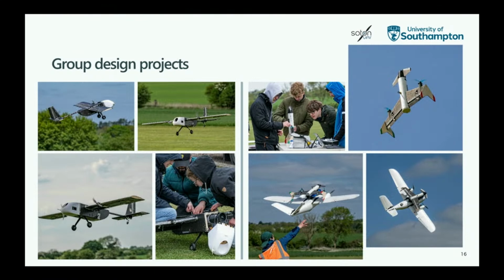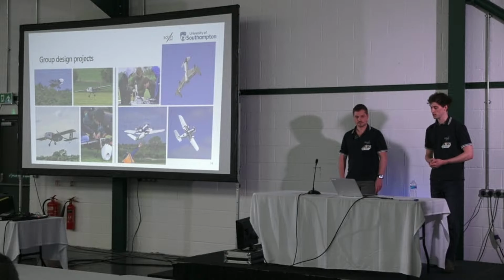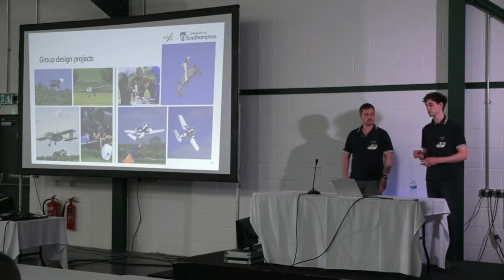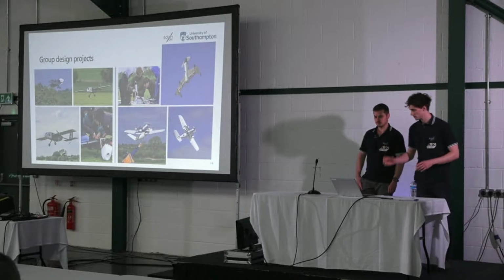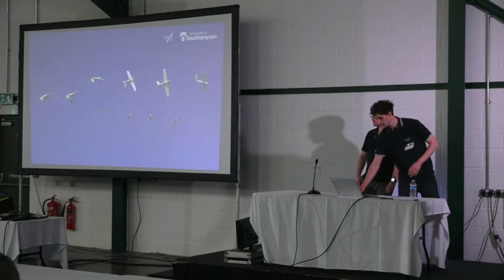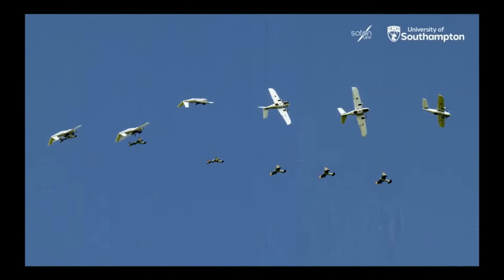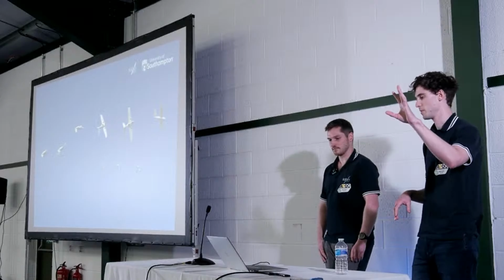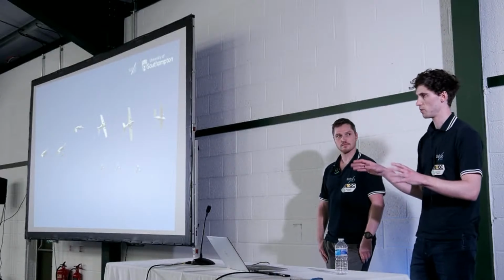The transition flew around, could do waypoint missions, come back, and transition back to its tail sitter configuration for a nice precision landing. This team went above and beyond and designed a release mechanism, attached it to this Believer aircraft, and then in quite a shuttle-esque fashion, we have the release there. The Believer would invert, drop the little payload tail sitter, and then the tail sitter flew an auto mission, came back, and landed, whilst the Believer mothership aircraft was put into a loiter or manually landed.